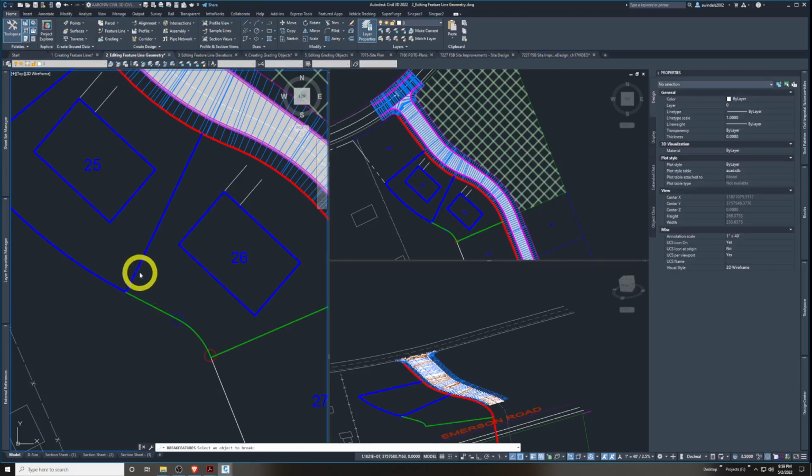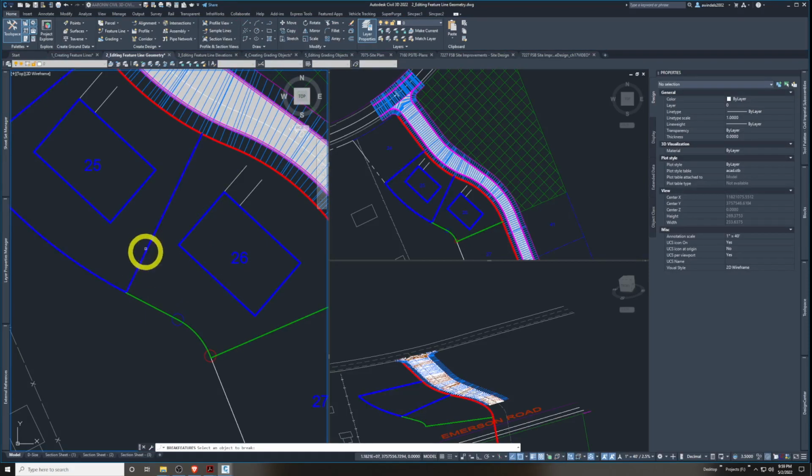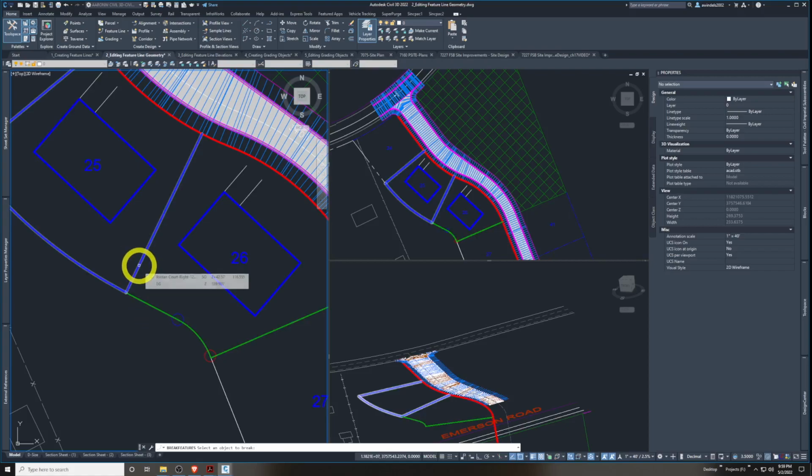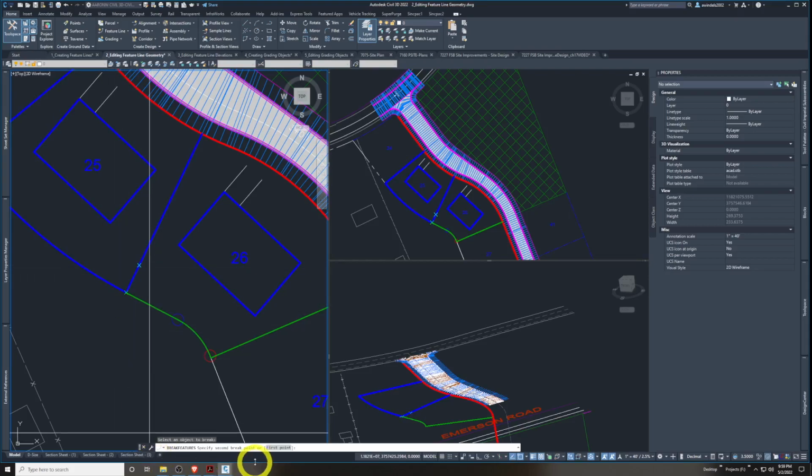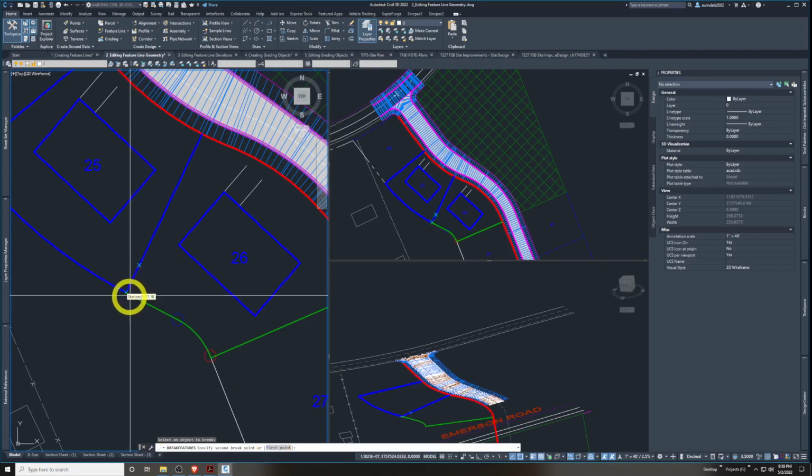And I want to select the blue perimeter now. I originally selected this one, but I want to break this feature line. So let's pick this. This one's good. I like to sometimes break at one single point, so it literally doesn't break out anything. If I picked one point twice, I would have a break with zero distance, which can be nice.